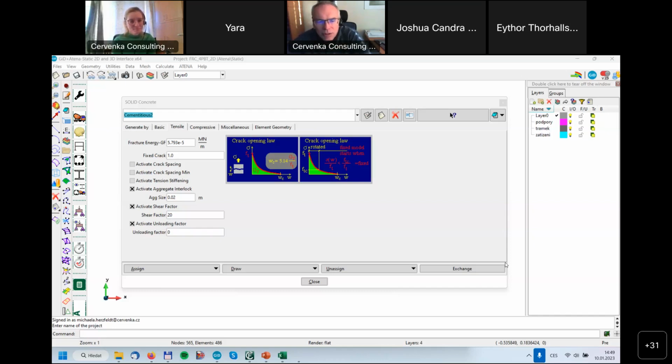So normally, what is best for fiber reinforced concrete is if you define your G over GC function such that it corresponds to this approach. Because you know your softening diagram for the fiber reinforced concrete, out of that you always know the unloading at each point. You can multiply by 20, and then you need to manipulate it a little bit, and then you can use it as this G over GC.